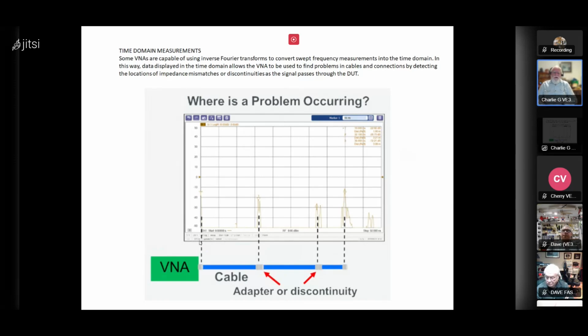It probably can, but I haven't been digging into it, mostly because I don't have one. But because you can do stuff in the time domain, you can do things like time domain reflectometry. Time domain reflectometry can do things like measure the length of a coax cable. If you've got a break in a cable somewhere, it can tell you exactly where that is.